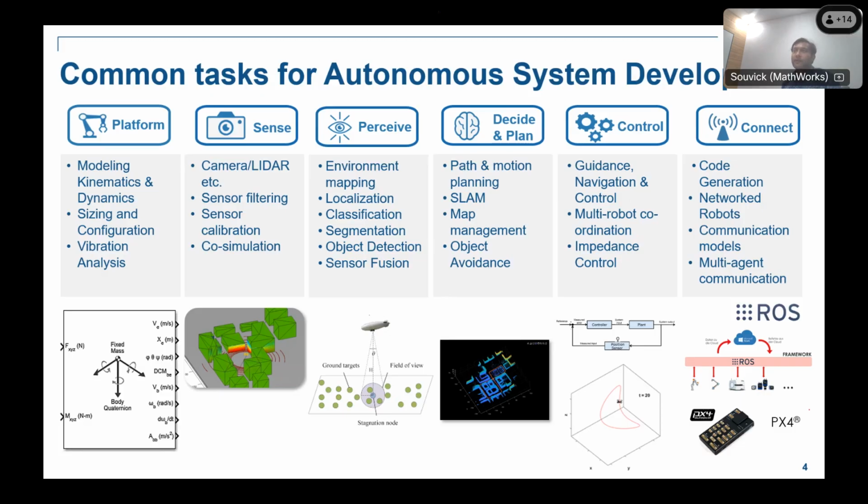So this is the full, end-to-end development of a UAV, or any robotic system, basically. This is how it works. UAV also follows the same operating procedure. If the platform changes, this part changes. If you have other types of robots, like a manipulator or a car, this will change. But in general, for aerodynamics or UAVs, we'll use the drag coefficients, the lift, and the 6DOF models here. Then this part will remain the same. Then we have to add the controller. The controller design will be a little different, but the rest of the things will remain the same in this context. Okay.